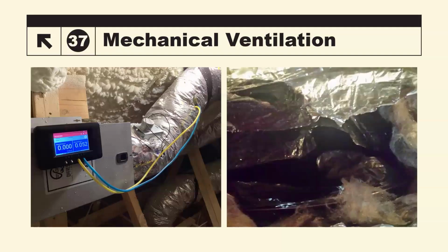And then lastly, with the 2021 IECC mechanical ventilation now being tested by an approved third party, the code requirement allows for various testing equipment that can be used. When this first came out and we were doing testing, the only way we had to test, especially if you're using a Honeywell YD150, is cutting into the ductwork. That's not the best choice, but as you see, if you don't prepare the duct to be cut first, as you see the one on the right, it completely shreds the inner mylar, and the duct just comes apart.